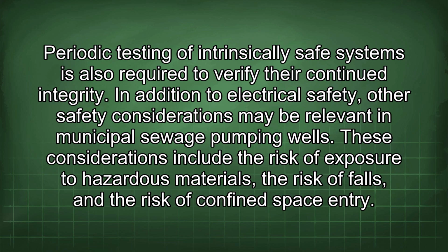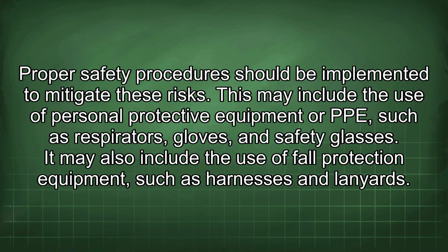In addition to electrical safety, other safety considerations may be relevant in municipal sewage pumping wells. These considerations include the risk of exposure to hazardous materials, the risk of falls, and the risk of confined space entry. Proper safety procedures should be implemented to mitigate these risks. This may include the use of personal protective equipment or PPE, such as respirators, gloves, and safety glasses. It may also include the use of fall protection equipment, such as harnesses and lanyards.